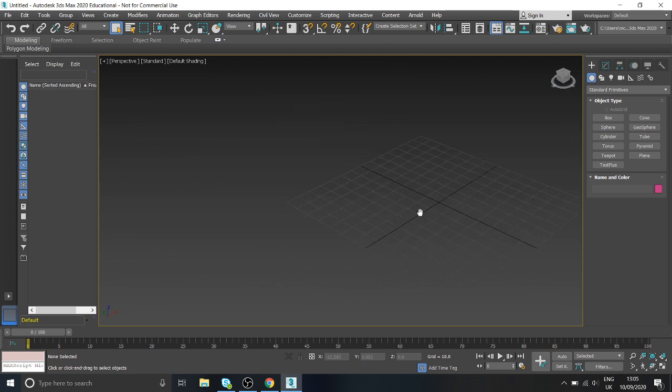Okay, so that's how you can move around side to side, up and down, and scroll in and out. But we've got a 3D space here, so we want to move around within the 3D space. To do so, if you hold down the Alt key and the mouse wheel, you see you can pan around inside that 3D space.